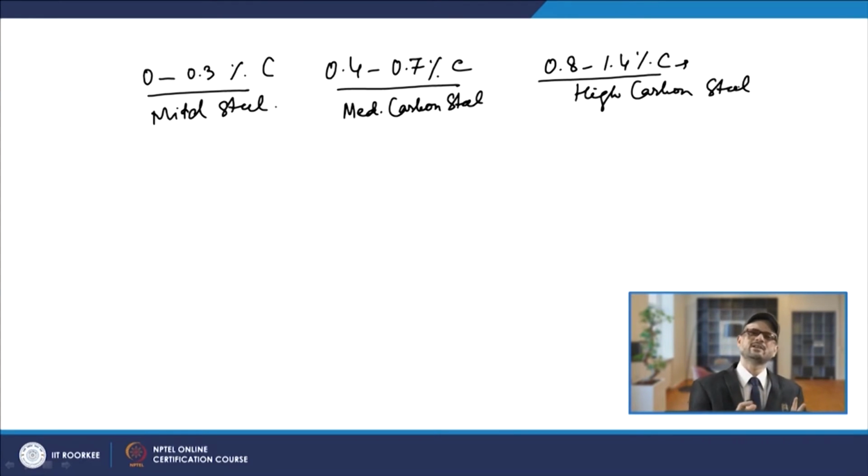Similarly, as we have already discussed for the varieties of cast iron, we use grey cast iron where we require damping properties. So, for most machine beds we use grey cast iron, because in that case you have the cushioning effect given by the graphite, which is the soft phase.